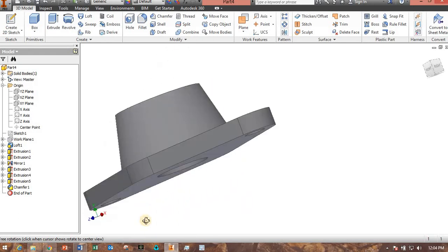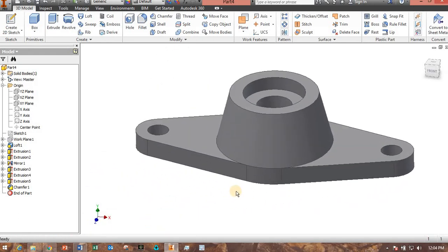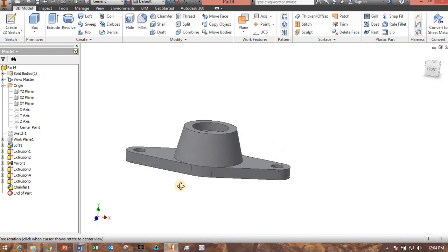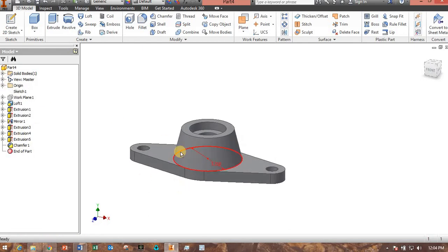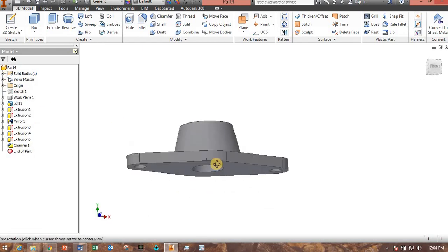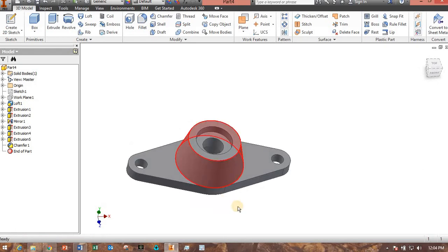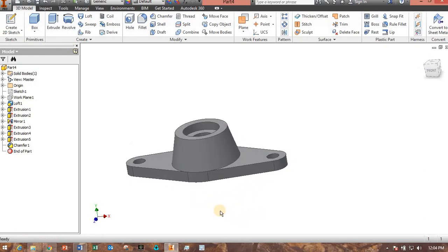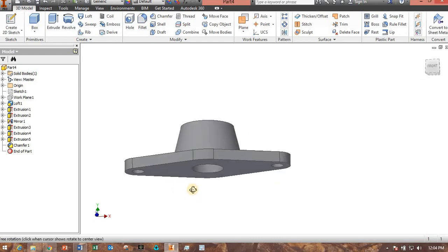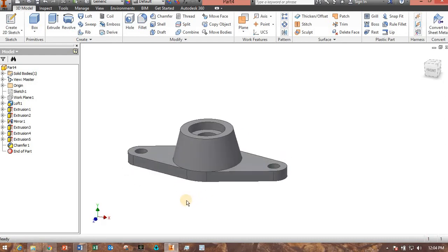Okay, so that's got the inside holes there. So that's the other way to do it, using the loft. Either way is appropriate. It really doesn't make much of a difference there. Alright, hope that was helpful to you guys. So we've seen how to make these parts that have an angle using loft, also how to make them with revolution, and then how to make extrusions in combination with revolutions to make this complex part. Hope that helps. Keep it up on the lab for the next parts.